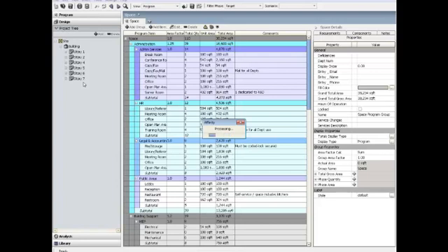The Generate Stacking function uses the information in the program to determine the size and number of apartments in the building. Then Affinity adds them to the stories from the ground up until they fill the 6,000 square foot area that I specified. Any overflow moves on to a new story.